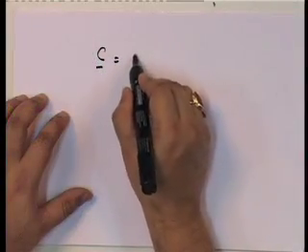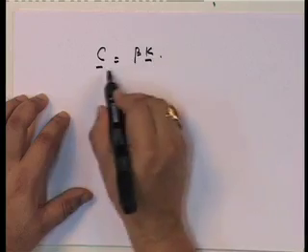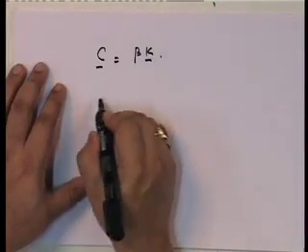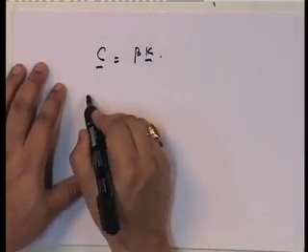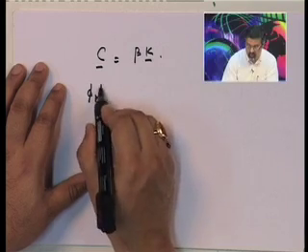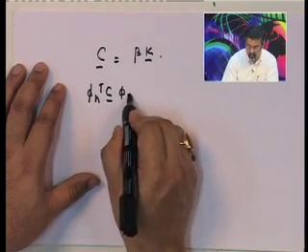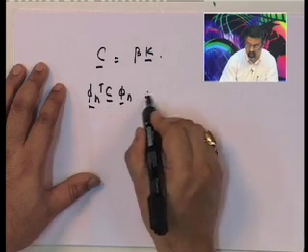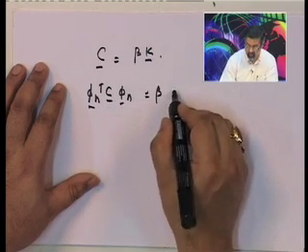Let us see what happens when I have stiffness proportional damping. If I have stiffness proportional damping, C is equal to beta k. So, let us go through it. Pre-multiply by phi n transpose and post-multiply by phi n.